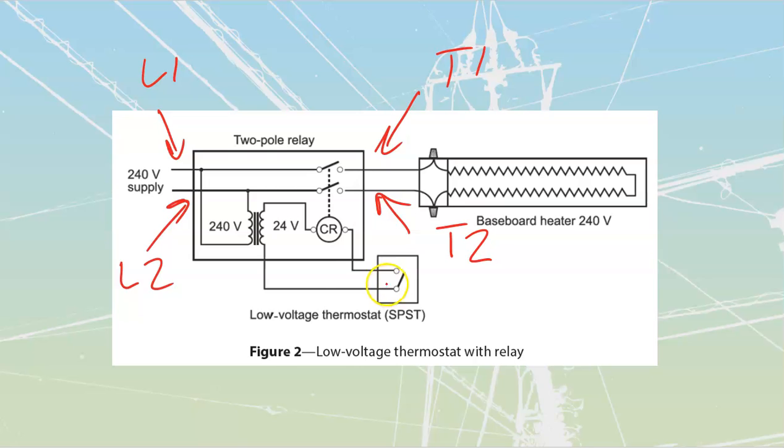And then we would usually have a TS. That is just going to be these ones here, and it stands for where my thermostat itself is going to go. I bring my lines into this side of the device, bring my loads out of that side of the device, and then I just connect a low voltage wire over to my thermostat itself. Allows it to go longer distances. You don't have to worry as much about cabling, etc.